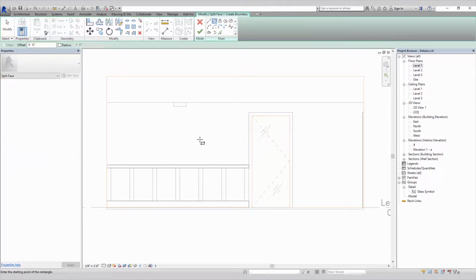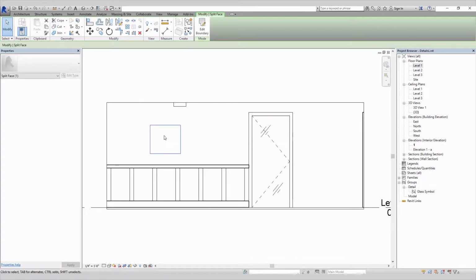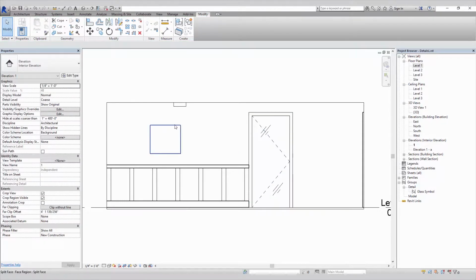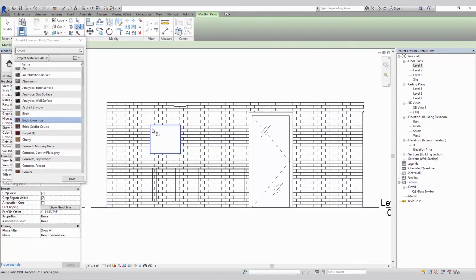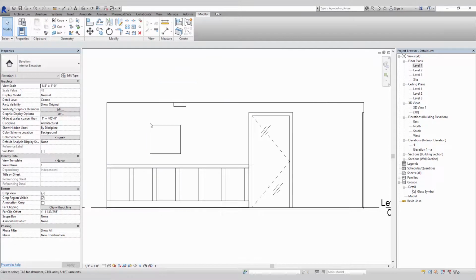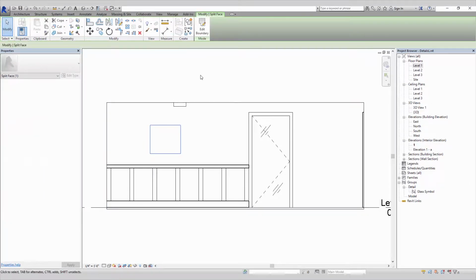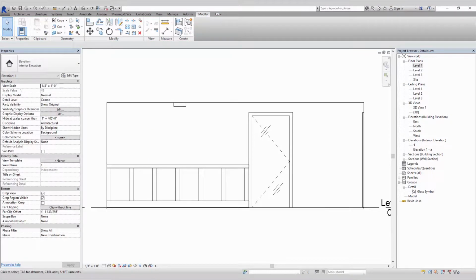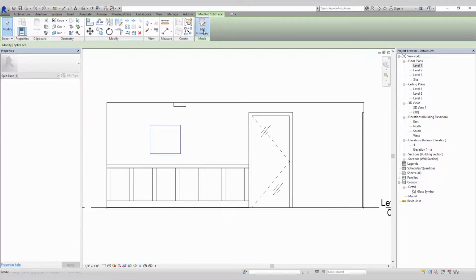And one thing to note is if you are doing a full region within the wall, then you can simply draw a shape like that, and it will change that for you. Okay, you can see once that shape is drawn, you can paint these independently. Or we could add a material to the wall and it will leave that part independent of the new wall material. We can also delete this once it's selected, or you can select it and do edit boundary.